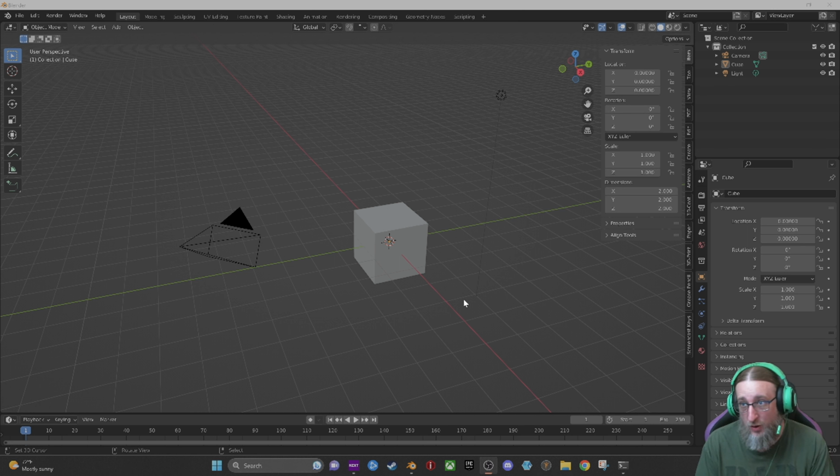And then we can scroll underneath, and all of those vertices are still selected. All I'm going to do is hit F to give them a face. Now it looks like some of them are sticking through, but in reality, they're actually not. If you zoom in, it's just a feature of Blender where, as you zoom away, it doesn't pull the vertices in correctly. So one of the ways to check that is just to zoom in a little bit, and you'll see that it clears up and you don't see any of that.